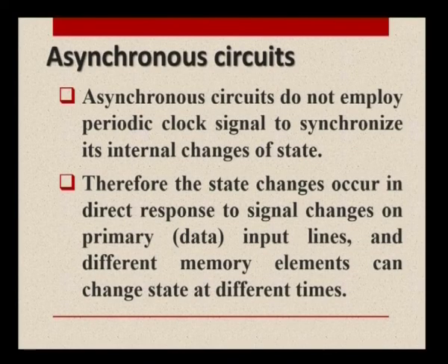Then what is an asynchronous circuit? An asynchronous circuit is the one which does not employ a periodic clock signal to synchronize its internal changes of state. Therefore, the state changes occur in direct response to the signal changes on primary input lines, and different memory elements can change state at different times.